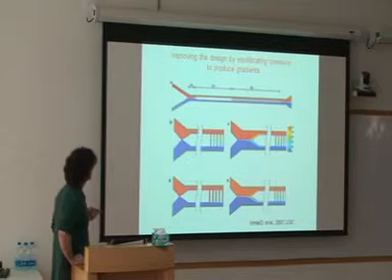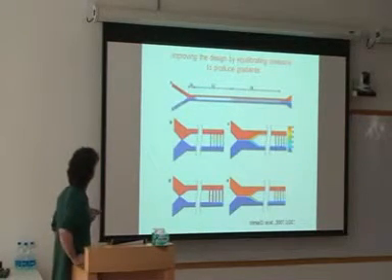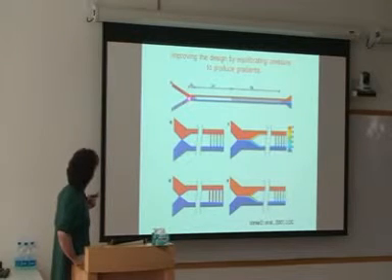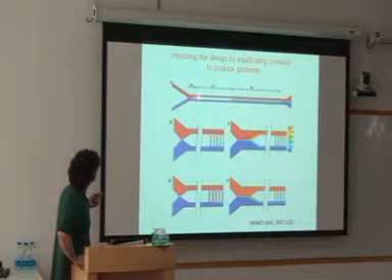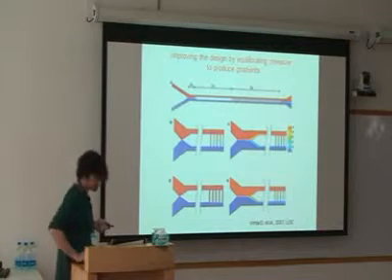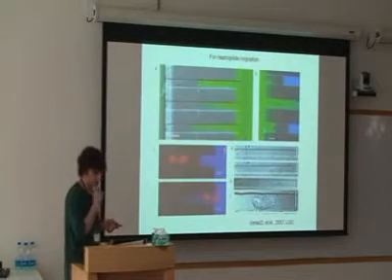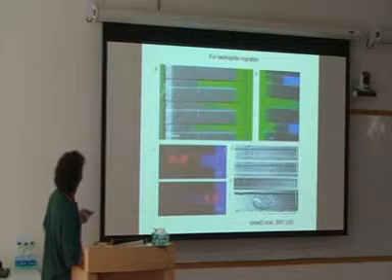And so you have different tricks, and these tricks I like because it's kind of automatic, you don't have to do anything special. It's just that you bring the two channels together here for a short distance, and so the pressure equilibrates here. And because it's lamellar flows, they don't mix so much. And with a little distance, so the concentration re-equilibrates, you get what you want. It's a nice trick, the kind of small trick that makes the device easy to use.